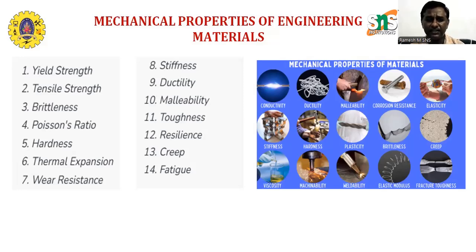Next is toughness. Toughness is the ability of the material to absorb energy and deform plastically before fracturing. It is a combination of strength and ductility. So it is important in applications where materials experience sudden impacts. Charpy and Izod tests are used to measure the toughness values.